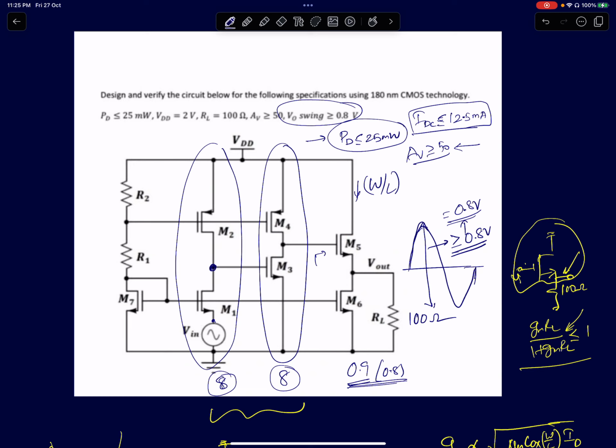So all I need to do is ensure that all transistors are in saturation. And when I say in saturation, even when the output is swinging, all transistors are supposed to be in saturation. That is something that I have to ensure by design. And I just said that the first two stages are there only to give me the voltage gain, and they don't need much power. See here again, noise is not mentioned, bandwidth is not mentioned, none of it is mentioned. Those will usually dictate the current numbers, but here none of it is given, so we don't have to worry about that. So for the first two stages I can burn as low current as possible and get the gain numbers that I want.